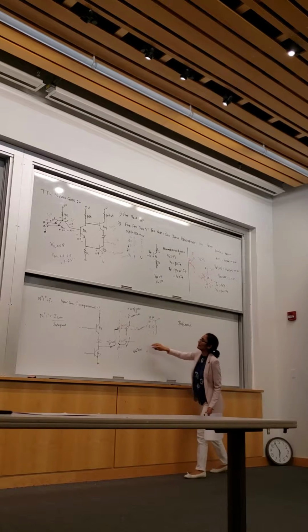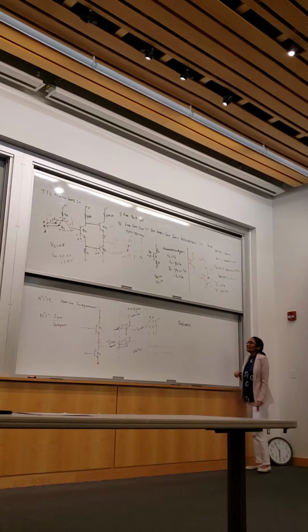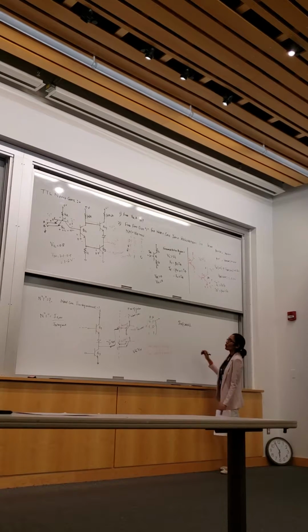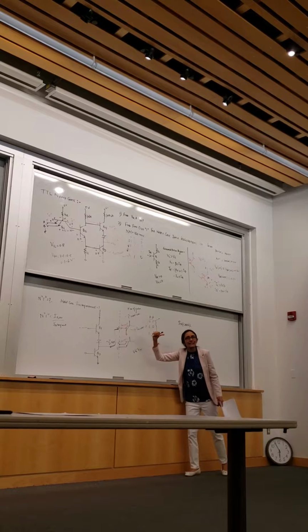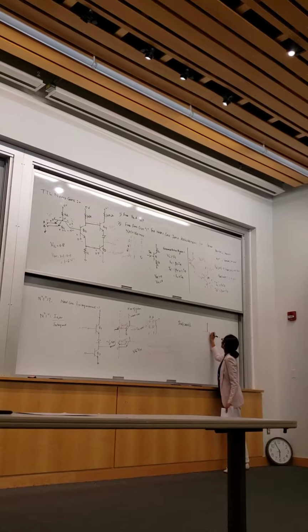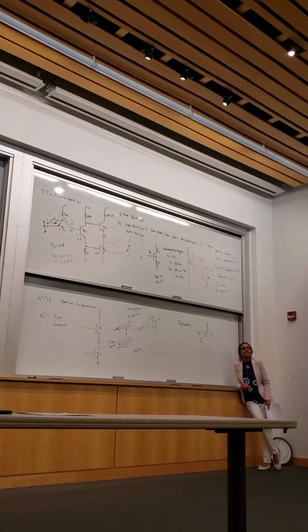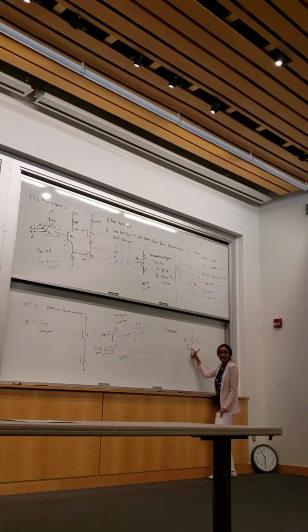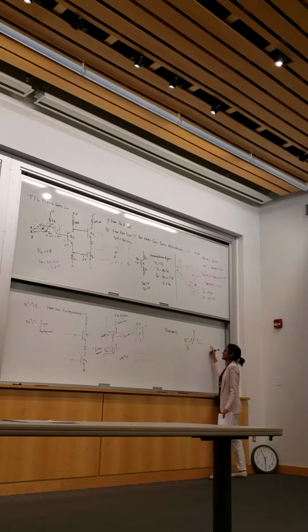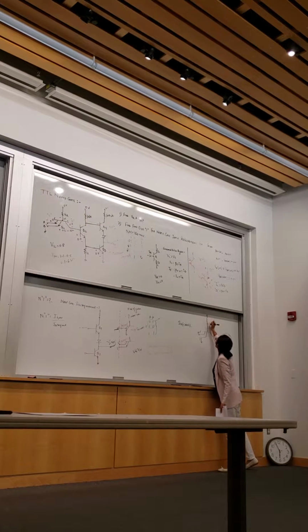So I'm going to do case 1. Case 2 is easy. Now for case 1, I'm drawing the input transistor of the next stage. This is at logic high, say 5 volts, and this is at logic low. And what happens here? So in this situation, because one of them is grounded, wouldn't most of the current flow through that grounded one? Yes. Basically, it's going to flow this way. So it's going to turn that off. We have nothing here. I have a resistor here. I don't know what the value of that resistor is. That's 540. Thank you.